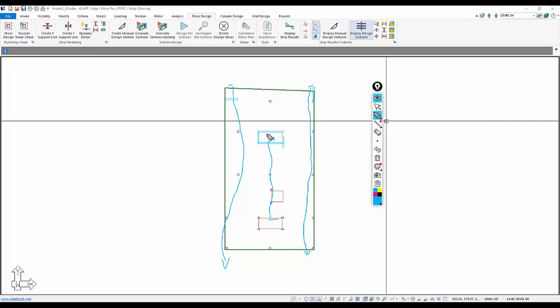Over on this side, we're going to do something like this where we stress out around that column. We might group that there, and then on this end I'll dead end a tendon here and do something similar on this side. So this could be done multiple ways. These are fairly long spans where we may not want to bring a tendon all the way through here with a low point in this long span, because we have some columns there that are affecting the behavior, the deformations of the slab in that region. So we'll leave it as shown without this tendon passing through continuously.